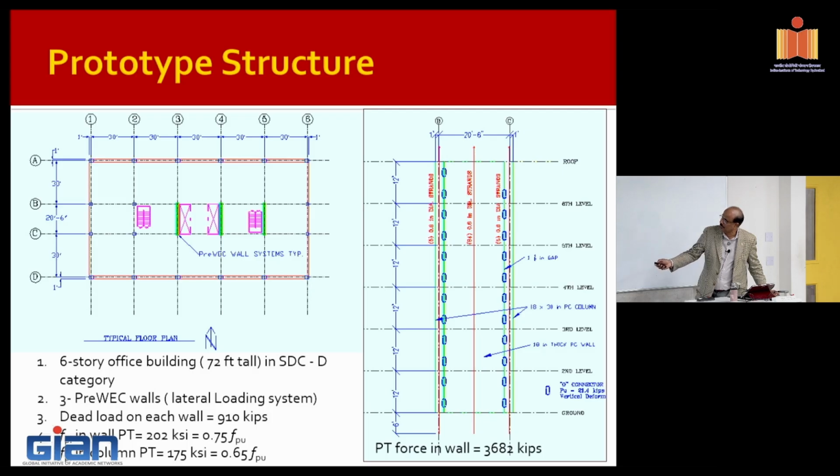So I just wanted you to know that they are not symmetric, but she wasn't concerned about adding another wall. Instead, she looked at what asymmetry would create. In this particular case, asymmetry also would put some additional load in the frame, and they have the capacity to take it. So purposely she chose to maintain that asymmetric detailing, because all she wanted was the 3 walls. Under seismic conditions, obviously the earthquake load comes in a different direction than what we assume, right?